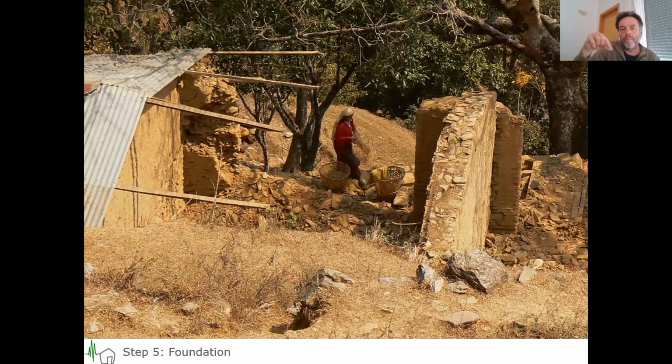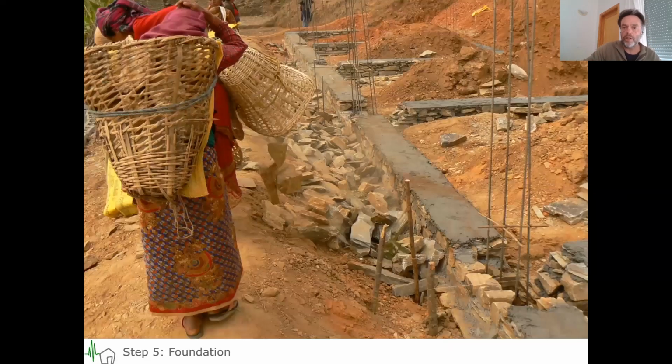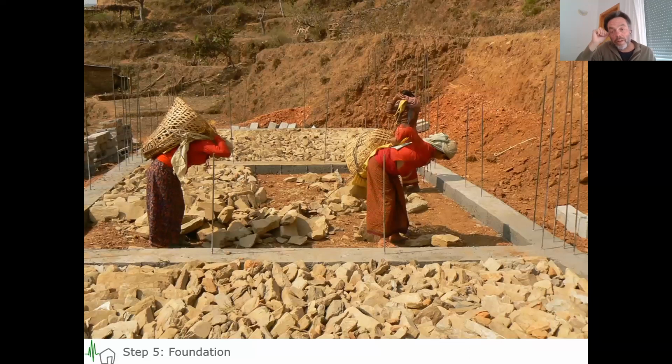We did a lot of recycling, so that's good. Again, to keep the cost down, but also this is people's participation, the contribution of the village, we started breaking down the old school building and recycling these stones. They had to be brushed a little bit, cleaned a little bit, but most of these stones went back into the foundation or into the floor filling, because why bother going into a very tough job of getting new stones out of the mountains.